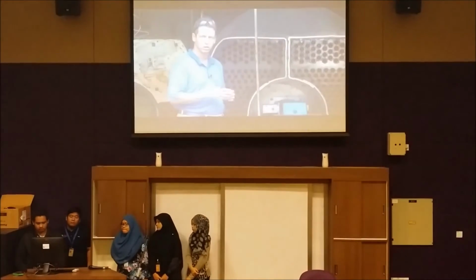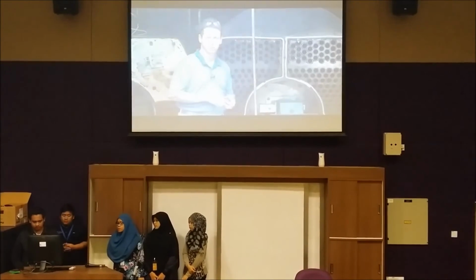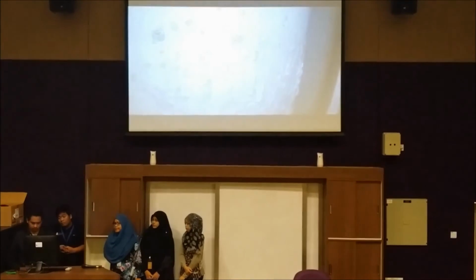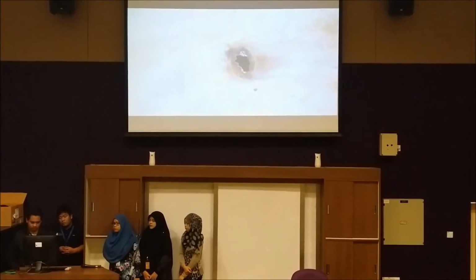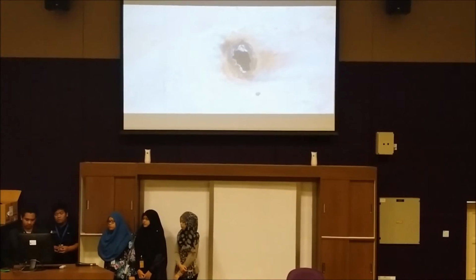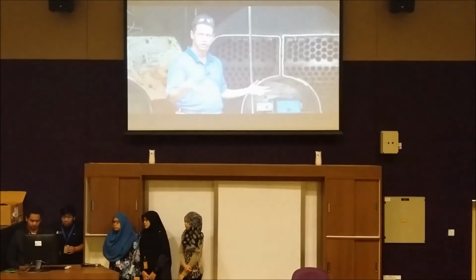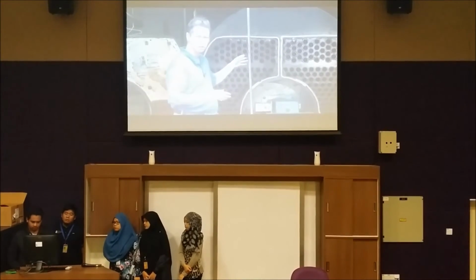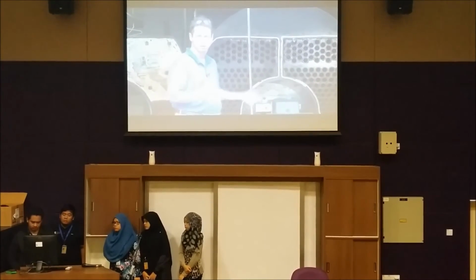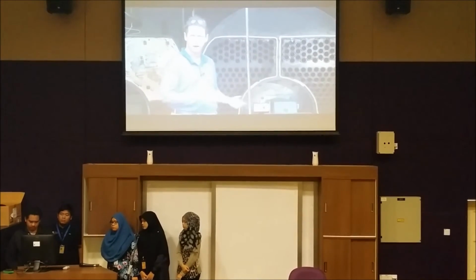General corrosion is another thing that can lead to boiler loss. One type of corrosion in the boiler is oxygen pitting. In the boiler, you'll see orange bubbled up marks on the tubes. As you move those bubbles away, what you'll see is it's drilling down into the tubes. You'll see craters in the tubes. As those drill down into the tubes, if they get bad enough, they're going to leak. They're going to cause a leak from the waterside surfaces of the boiler to the fireside surfaces of the boiler. We'll see corrosion coming out of the tubes if it gets bad enough.